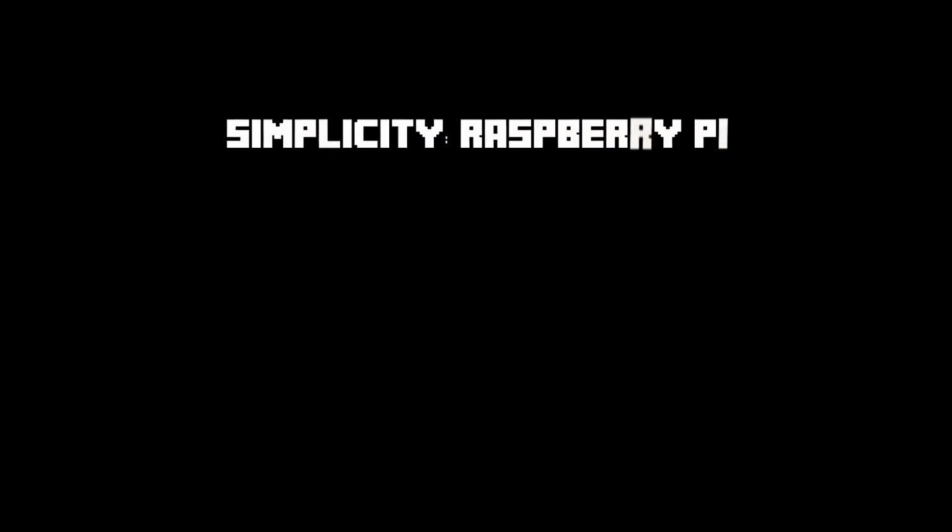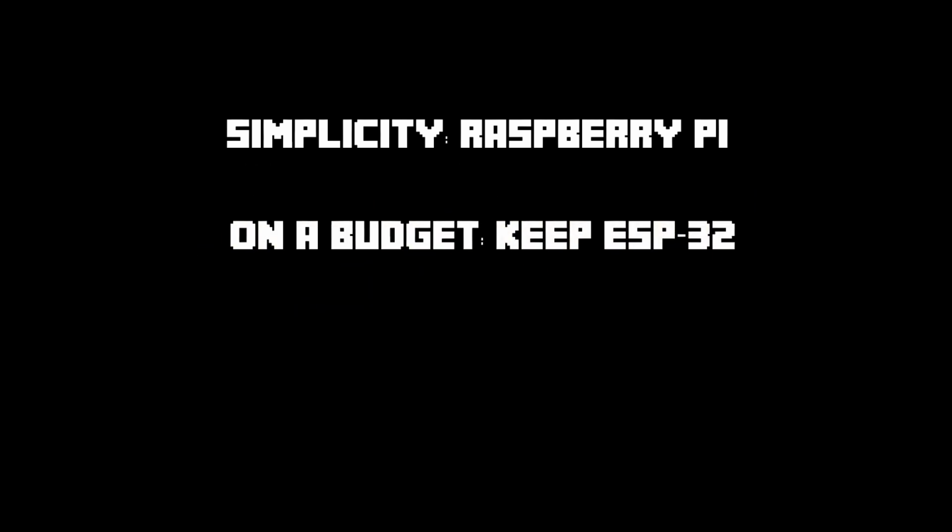The following recommendations are made for future iterations. For simplicity, use either a Raspberry Pi as the uplink or a microcontroller with both Wi-Fi and sub-1 GHz radio as the gateway and uplink. If cost efficiency is a factor, it is recommended to keep the modular design with an ESP32 or similar as